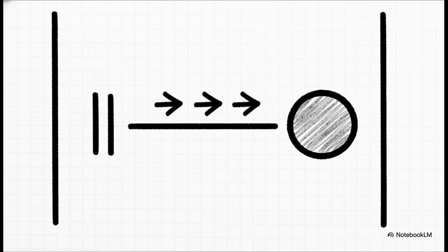First, imagine power flowing continuously from the left vertical rail to the right vertical rail. The horizontal lines are called rungs, and they represent individual conditions and commands. That symbol that looks like two vertical parallel lines indicates an input, or a contact. And the parentheses symbol at the far right indicates an output, or a coil.